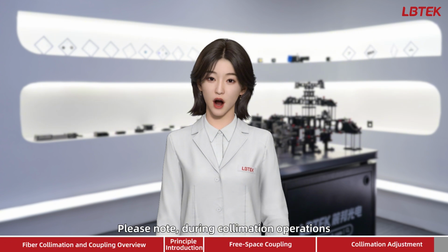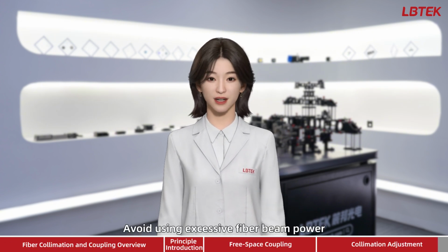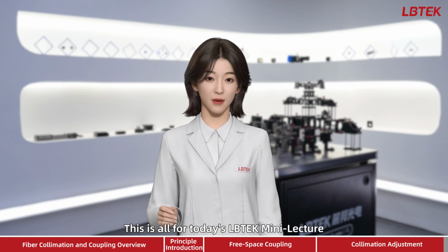Please note, during collimation operations, since the spot size is small, avoid using excessive fiber beam power to prevent damage to the beam profiler. This is all for today's Lubin Optics Lab.